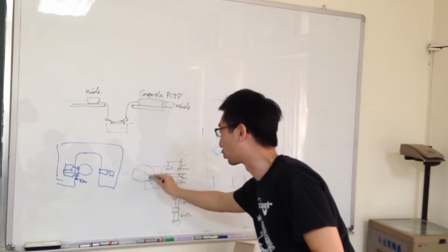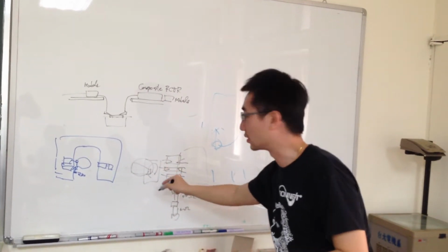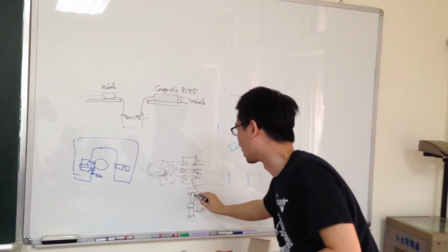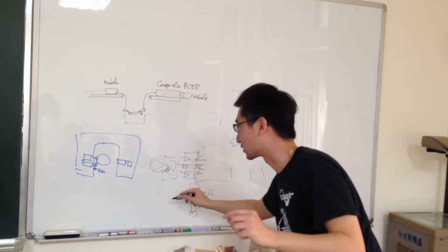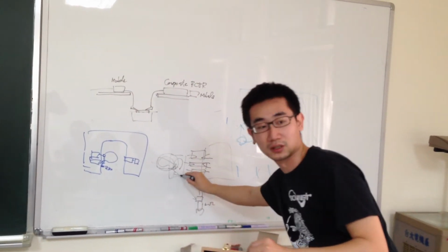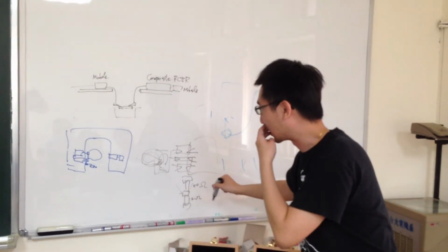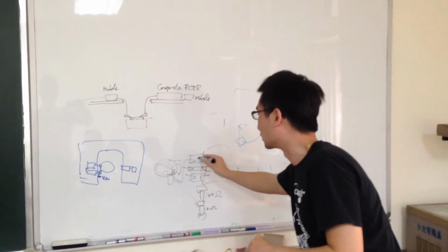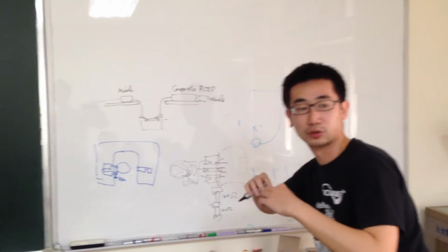Yeah, but this pole will have its loss and it affects the noise figure directly. And this terminator, there is also some mismatch between these two terminators. So I'm wondering if we can just use a through, maybe we can make these two ports very close.